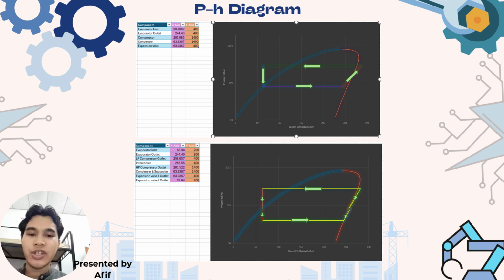So now moving on to the PH diagram for both the unmodified and modified versions of the refrigeration cycle that we have obtained and made together. The first construction of the PH diagram represents the general refrigeration system using the values obtained. The first horizontal bottom line is represented by the evaporator, and the slanted line going to the right and above represents the compression, only single compression, followed by the left of the graph, which is represented by the condenser, and the expansion valve going straight downwards and connecting back to the evaporator itself.